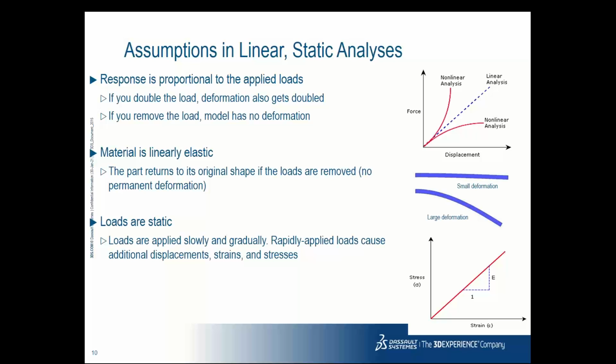If I apply a load, the component won't pass the yield point, and as soon as I remove the load, it will regain its original shape. That is what elastic means. One more assumption is that if I apply a load of, let's say, 100 Newton, I get a displacement of 2 mm. If I increase the load to 200 Newton, due to the first assumption, we will get a displacement of 4 mm. Since we increase the load linearly, the deformations vary accordingly. This is one of the assumptions.